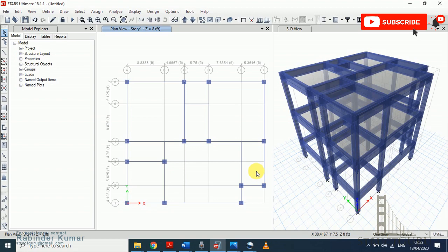So if we are considering the rectangular section, the total moment of inertia is BD cube divided by 12, we all know that. But when you make this member of concrete, it will experience cracking when loading after some time. This cracking will occur when concrete reaches its tensile capacity, which is about 7 to 10% of its compressive strength. For example, 4000 psi will have only 400 psi of tensile strength if we are considering 10%. After cracking, concrete is no longer able to carry tension, so steel starts taking the tension.